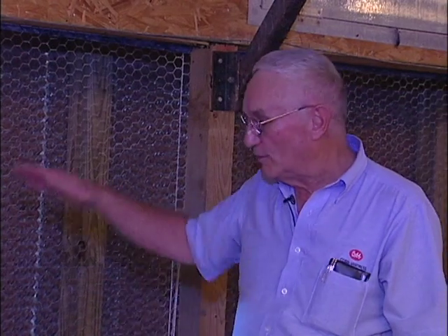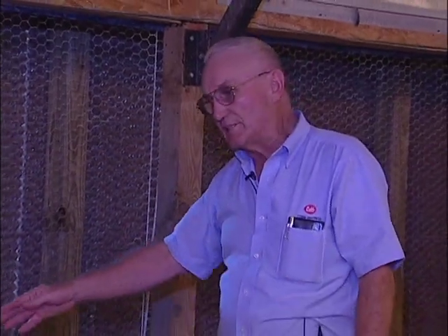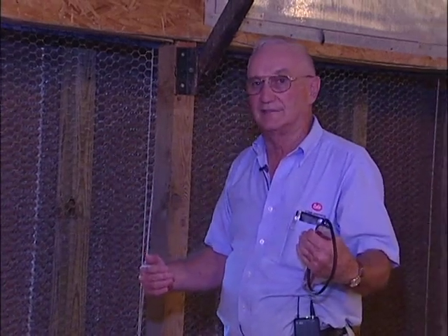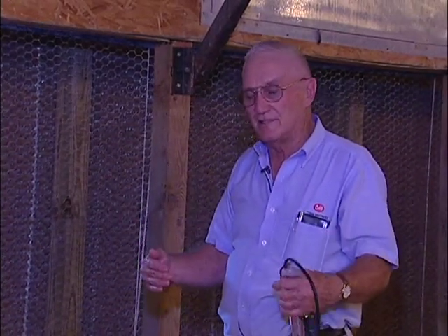And the biggest problem that we have here when the inlet curtains are all the way down to the floor, we don't have enough restriction. So what it does above everything else, it creates bird migration. If the birds can feel the air coming into the house, they tend to want to migrate to this section of the house. So it creates migration.